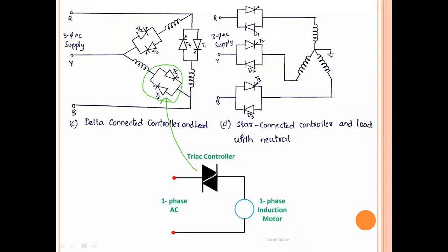Since AC voltage controllers, of both single phase and three phase, allow stepless control of voltage from its zero value, they are also used for soft start of motors. So in order to start the induction motor with a soft start, these controllers are very much helpful. With increase in firing angle, both distortion factor and displacement factor reduce, which reduces the power factor.